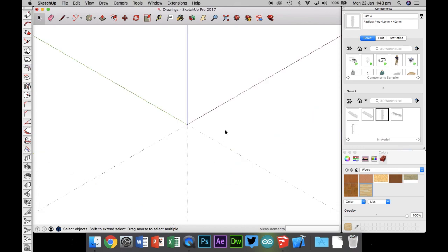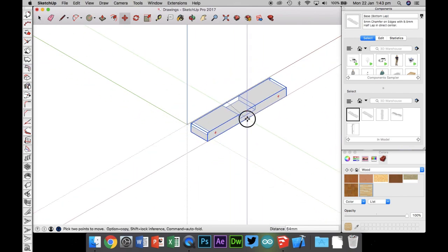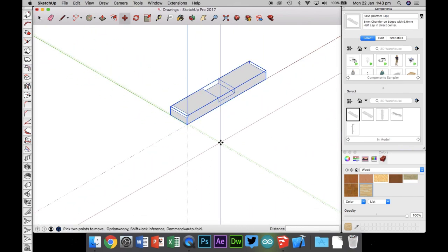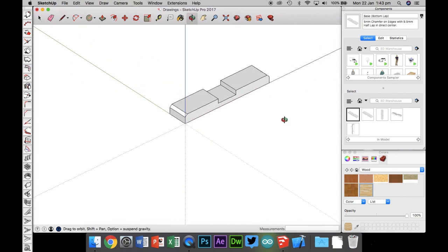At this point, we actually don't need all 3 projects in, and they don't need to be rendered anymore. They don't need to have the timber color, they just need to be plain black and white with some gray. So I'm going to select one part to start with, snap that into position, okay, and I'm going to need to send this to Layout. Now we're currently in SketchUp. Layout is a part of the SketchUp program that is specifically made for doing drawings.